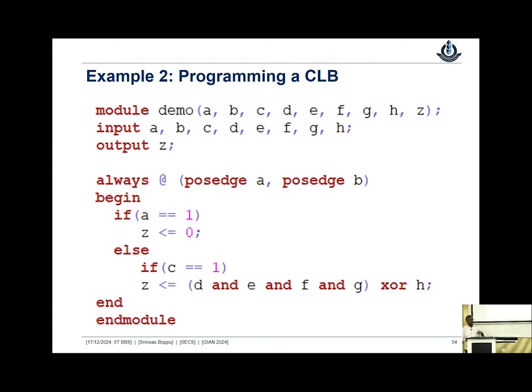So the sheets are there. Looking at the combination logic, here we have Z equal, of course, with this non-blocking statement. This whole expression is going to be your combination logic, and then of course we need to assign it to Z. Definitely Z is going to be a flip flop, and the same explanation which I gave you earlier applies.